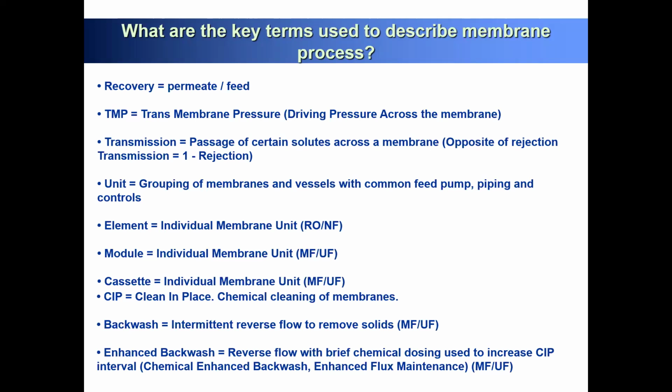So in general, when you design your seawater desalination plant based on your scenario, so we have 3.5% seawater, the recovery is 45% or 50% possible. So when you design what's the recovery you like to target, so you can just fix the 50%, then you can start design for your plant, or 45%.